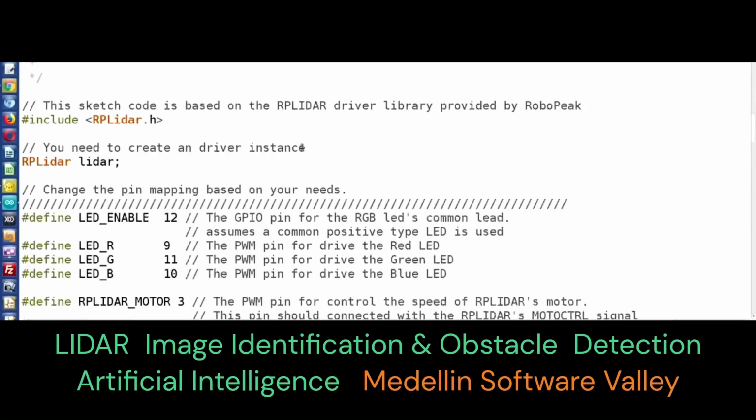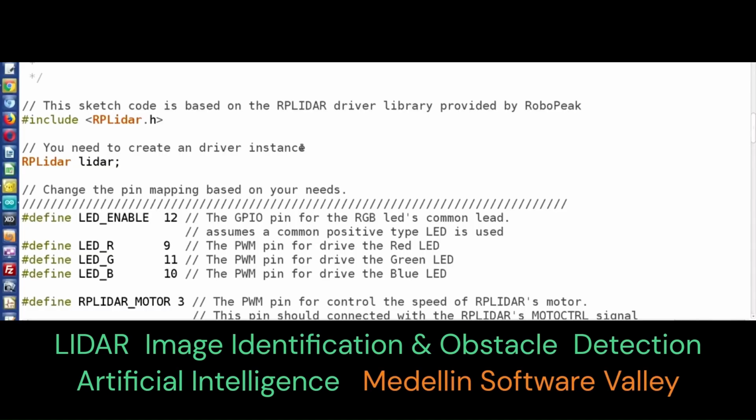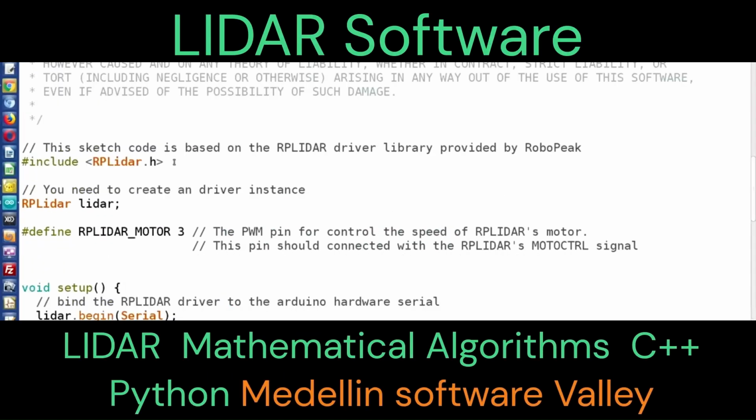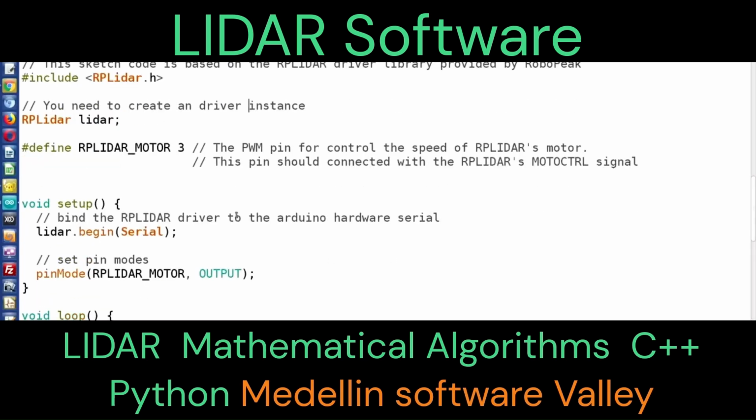In the LIDAR architecture, in the transmitter, the pulse is generated and amplified by the laser driver. The resultant laser beam is then transmitted through the optics. In the receiver, the reflected light signal is detected by the photodiode, which produces a current proportional to the return signal strength.